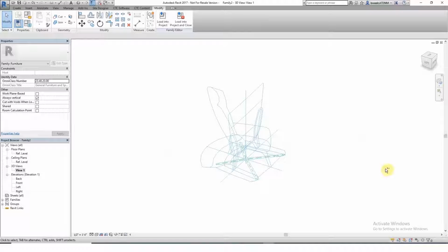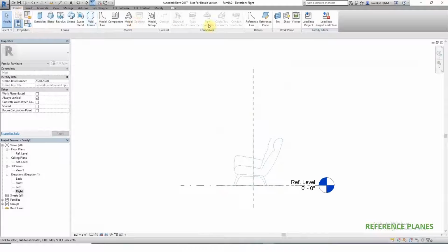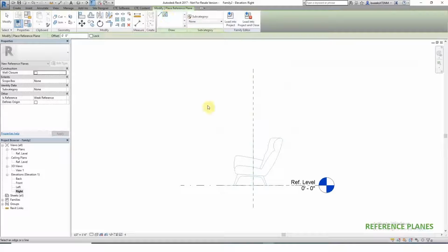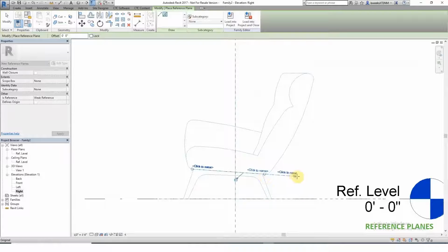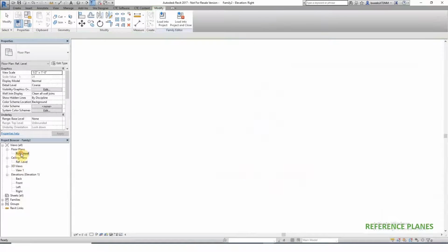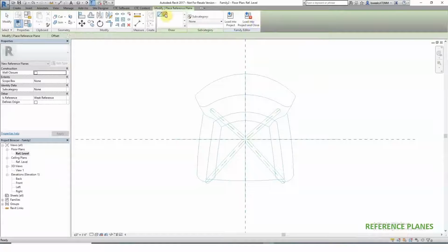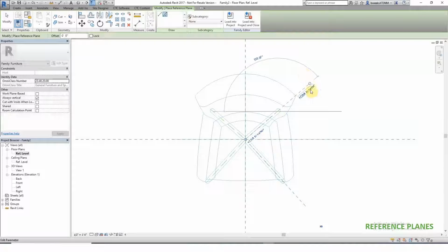All right, so now that we've got the CAD layout, the DWGs, the next step is we're going to create our reference planes. If you recall the previous slide, we have three reference planes: a chair seat plane, a front leg plane, and a rear leg plane. So I clicked on reference plane at the top. I selected the line tool to select that line from the DWG, the base of the seat, which created a new plane. And then I'm doing the same for the front and the rear legs, and then I name them, so that I can refer to them as I'm creating the forms.